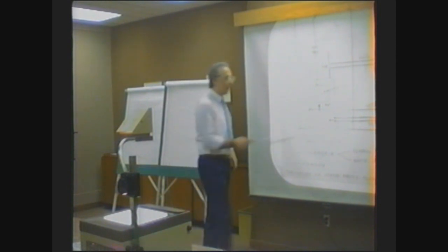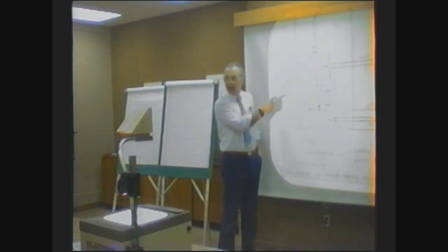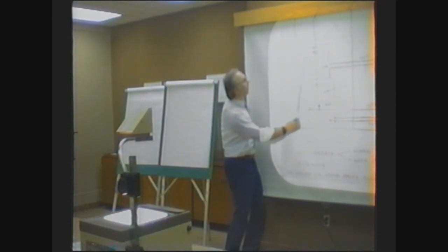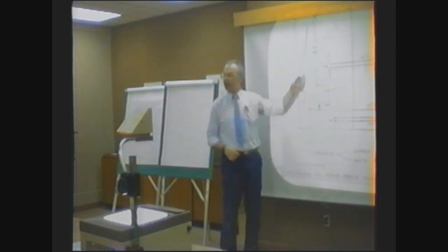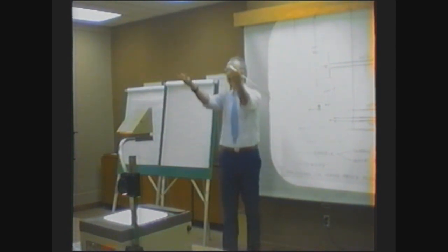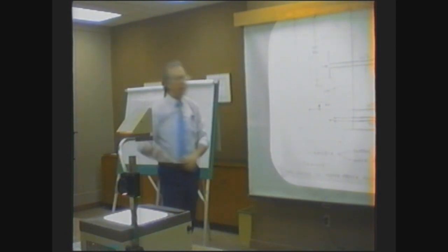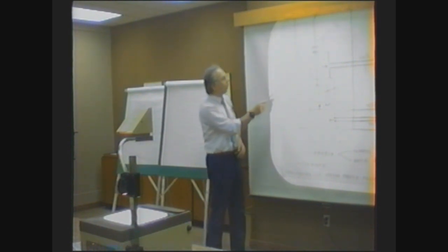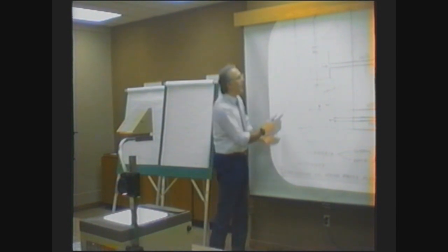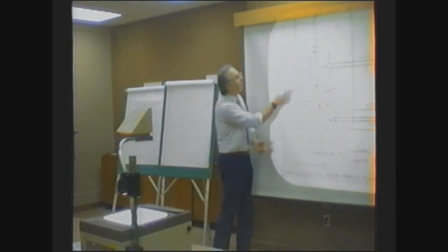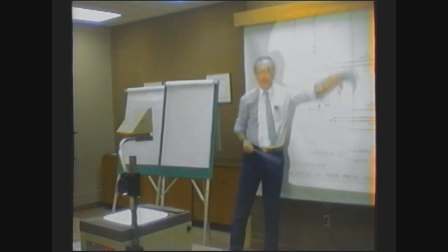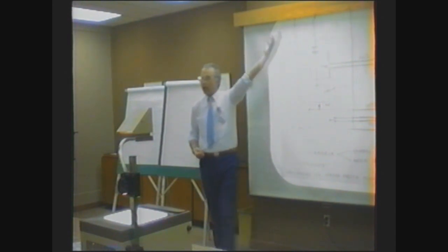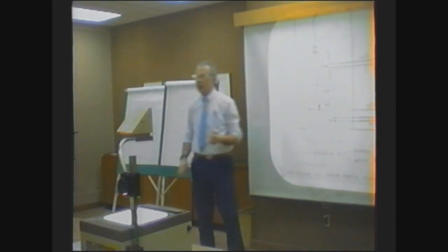The reason is simple. We know very well that radioactive particulates are created, and because they are very light, they go towards the surface of the pool, and they are going to emerge at the surface and are going to have a lot of radiation. In order to avoid such a thing, we have a small quantity of water here. This water, because it's outside the plenum, creates a flow going that way. But because the system is closed, the water doesn't go to the surface; it has to go back to where it came from. By going back, it takes all the particulates back and puts them through the system. So the radiation at the surface of the pool is not very big.